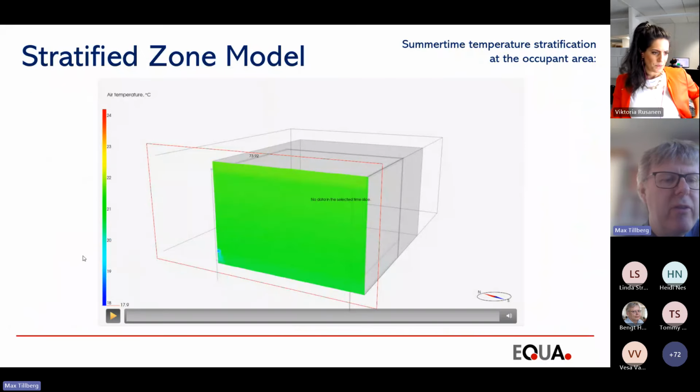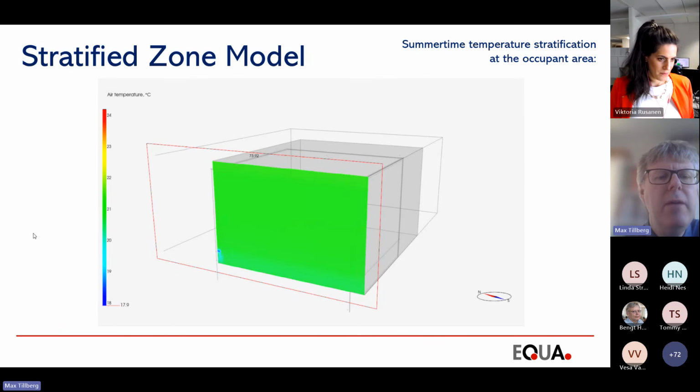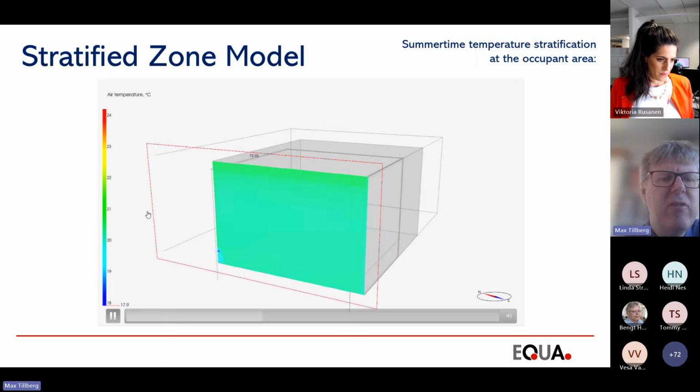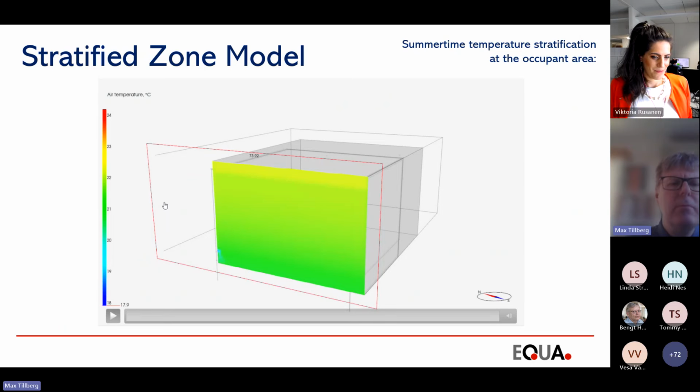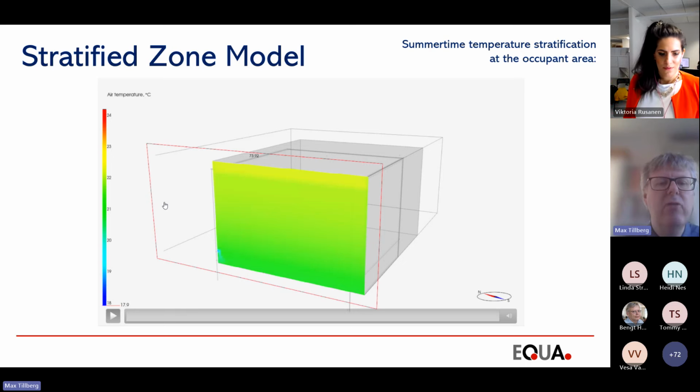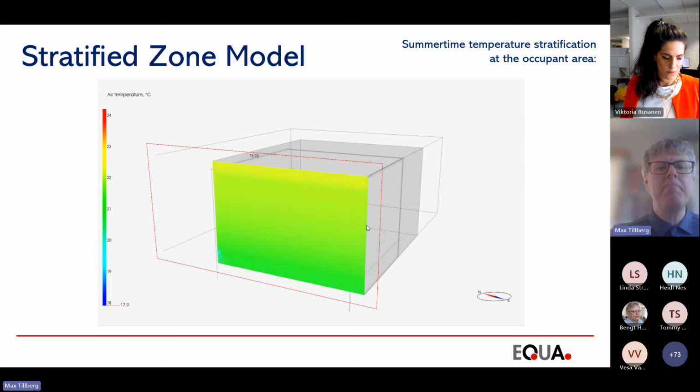And we can look at this as well for the summer, just for fun. And this is the air temperature that we are visualizing for this day. And we see here that this is the effect of the ventilation, and here we have the internal loads again. And here we also get a stratification. We knew about the stratification already since we looked at those charts before. So here we could, for example, look at how we could reduce the ventilation flow rates and things like that, depending on just looking at the area where people actually are located.